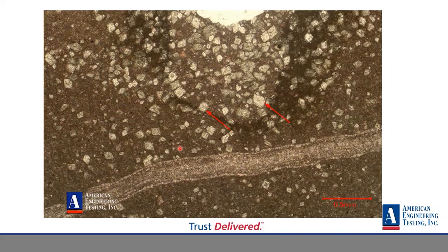Now I say there's much less understood about this reaction. What people think for alkali-carbonate reactivity is that the dolomite de-dolomitizes and produces another mineral called brucite, and that brucite is what would cause the expansive properties.